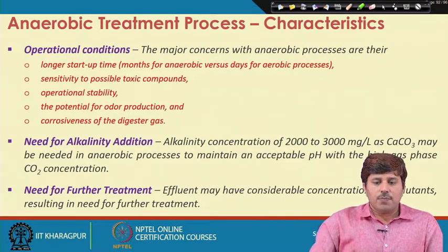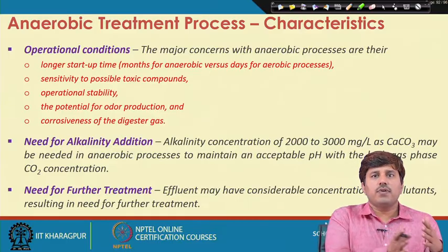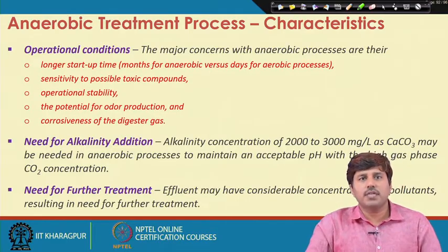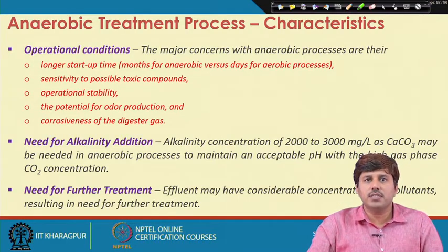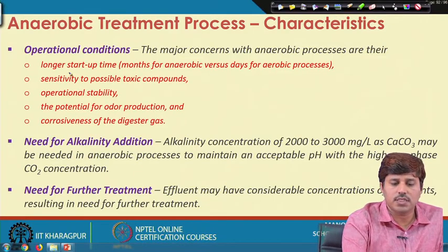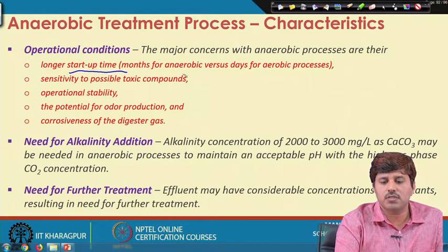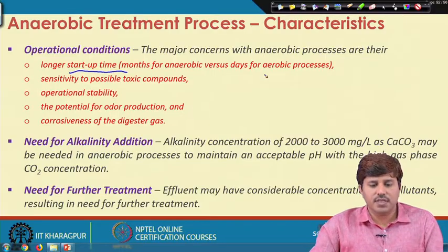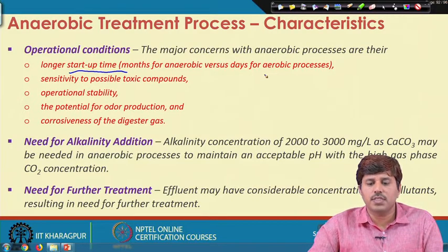Now, if we look at the operational conditions, we talked about various positive aspects, but there are negative aspects as well. The major concerns with anaerobic processes are their longer startup period. As we discussed, it may actually go for months, as opposed to a few days in aerobic processes.